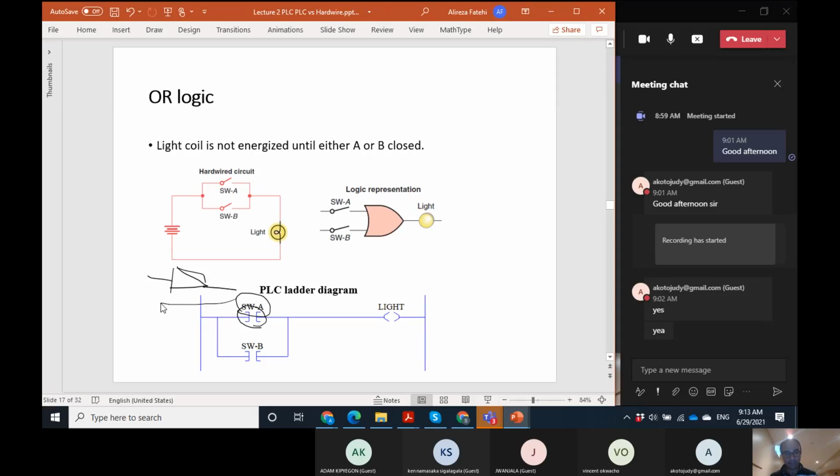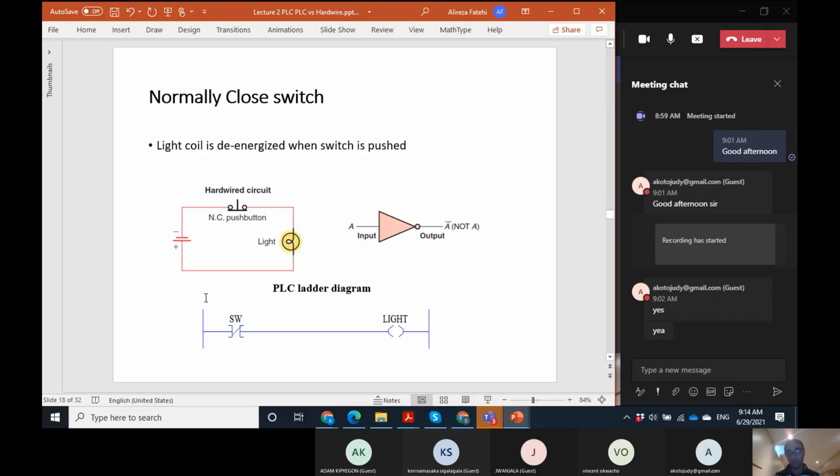The state of the variable is the state of the input of the buffer, and the state of the contact is the state of the output of the buffer. For the buffer, they are the same. But the important part is the NOT logic. The variable address that we see here is the state of the input, and the state of the contact is the state of the output.